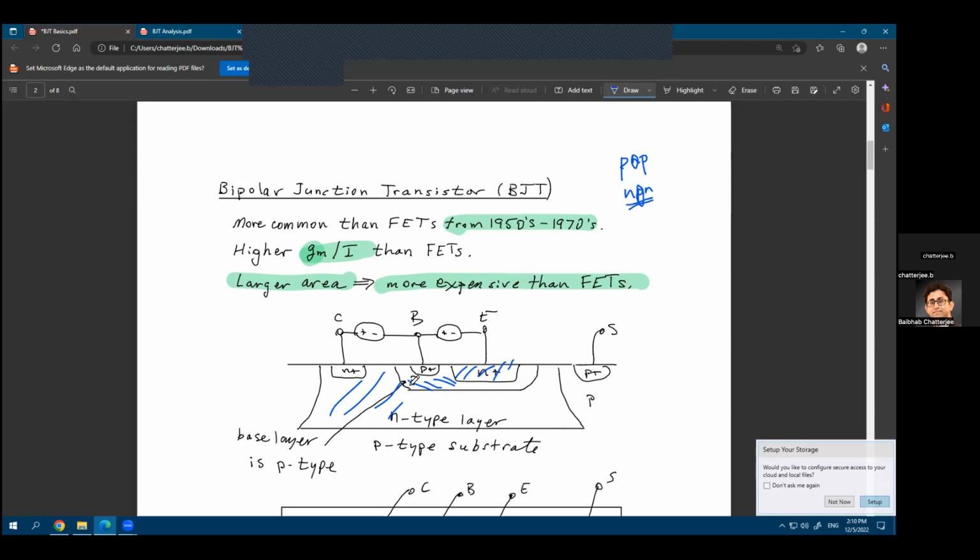Here you don't have a continuous N-type semiconductor, so you're more reliant on the drift of the carriers. When you study a semiconductor physics class, you will learn the differences between the drift current and the diffusion current. When the device is on, it mostly happens through the drift current, which I am giving as an analogy of this inertia. So this drift is basically analogous to the inertia that I am talking about.